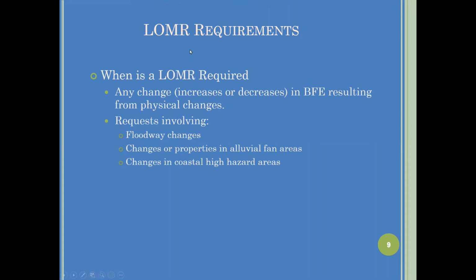Letters of map revision requirements. When is it required? Any change, an increase or a decrease in the base flood elevation resulting from a physical change, and any requests that change the floodway, properties that are in alluvial fans, and changes in coastal high hazard areas.